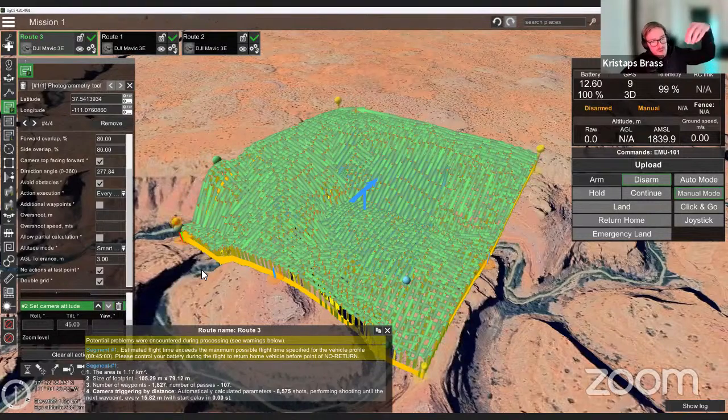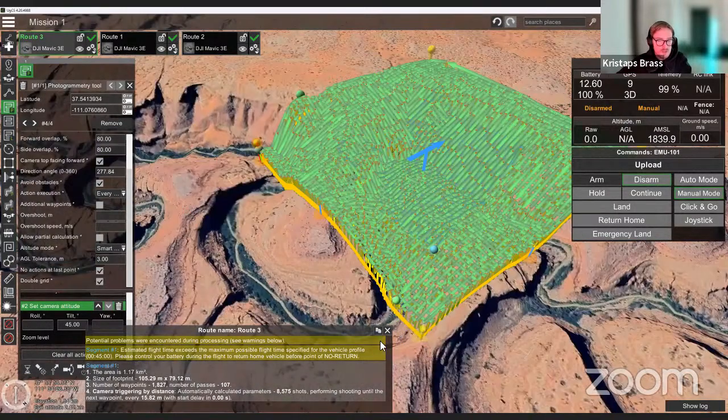So the idea would be that you fly from one altitude where you just capture those nadir images at 90 degrees, and then you go a bit downwards. At a slightly lower altitude, you capture images at 60 degrees, and then at 30 degrees. By having those 3 different angles, you're able to create a more accurate model than you can with just 90 and 45. So that's just a suggestion which you can try if you want to do those types of flights.